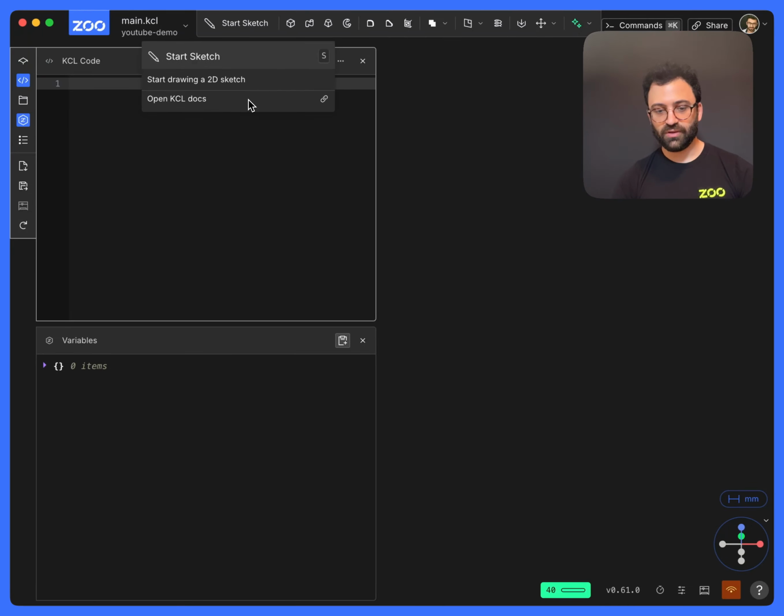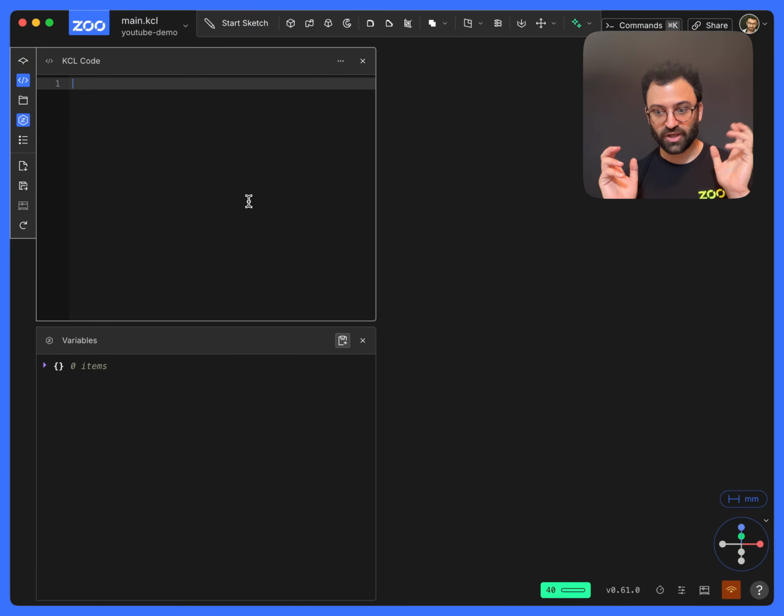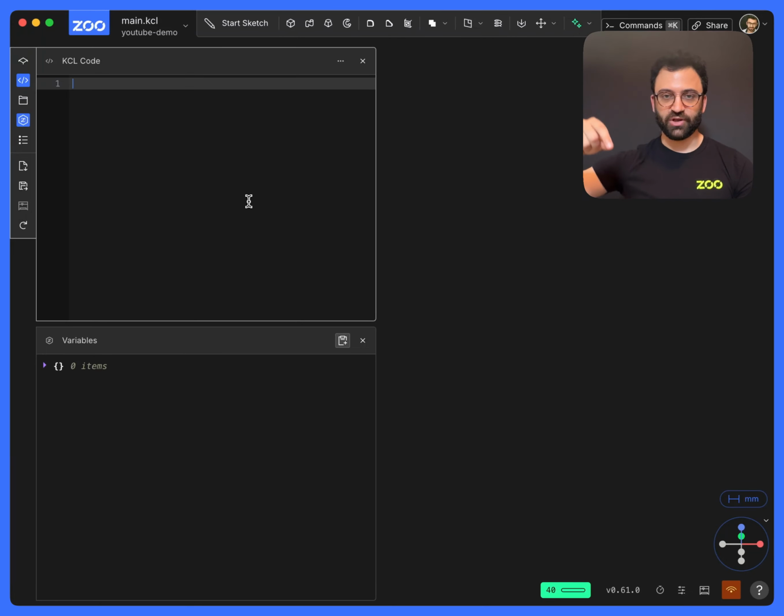In traditional CAD, people do a kind of sketching workflow. Basically, the way sketching in CAD works is you start off by choosing a plane, like a flat surface, to sketch on. And then you choose a point to start at, and you draw some lines on that plane. You're going to draw some lines, and they're going to join up, and where the line loops back on itself, you'll stop, and you'll make a closed 2D shape. And then you'll find some way to take a 2D shape into 3 dimensions, like maybe you pull it up into the 3rd dimension. So we're going to see how to do those things in KCL.